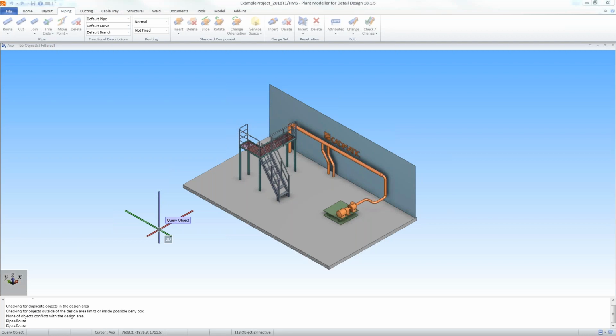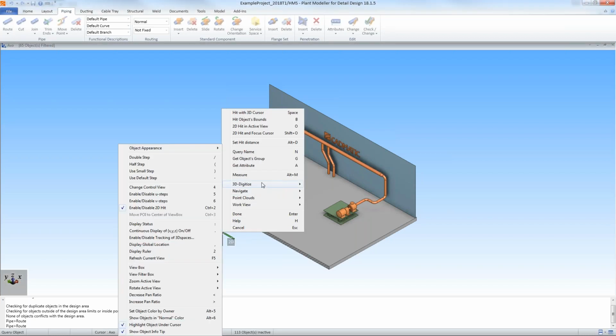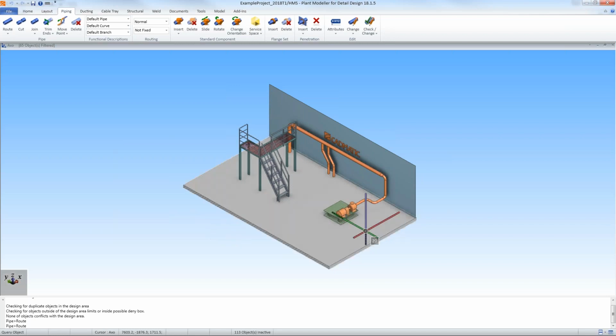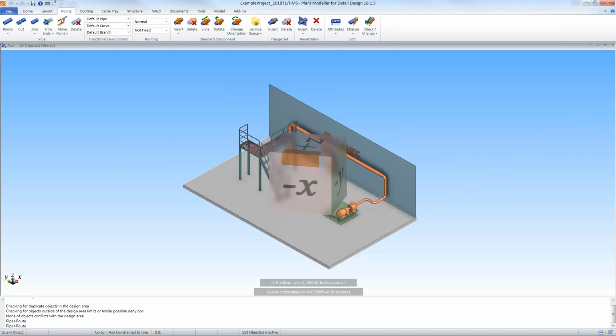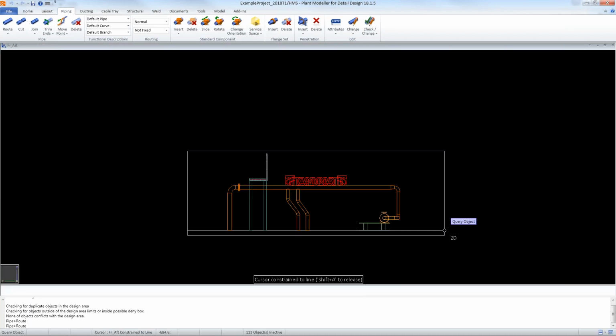So there's a question about using Alt-3 in axonometric views. I'm not quite getting the question, but it is apparently relating to the move viewpoint to current location. So the way it works is if I move here and use Alt, let's say here, it will cut my filter box accordingly, from the front plane.